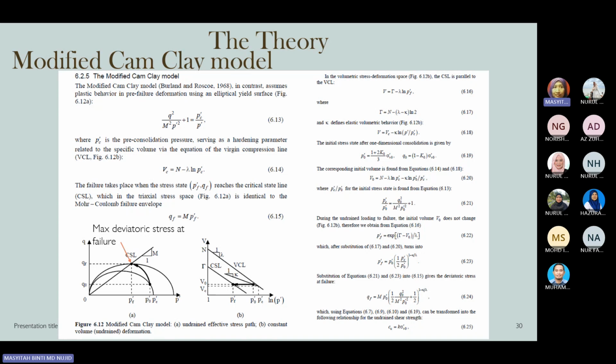And it also involves the critical state line, because the Mohr-Coulomb model cannot explain where the critical point of the soil condition is when subjected to loads. And here, when you have the Modified Cam-Clay or the Cam-Clay model, it can ideally show what is exactly happening in the soil during shearing or during the applied loads. So this is true when we look at the soil behavior.